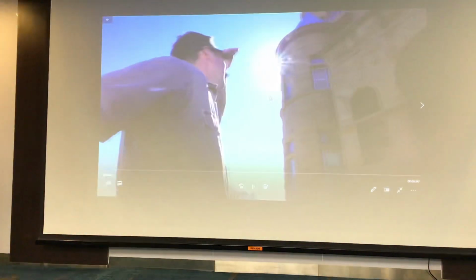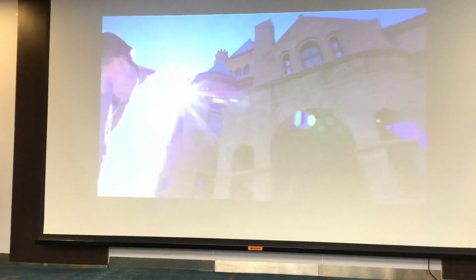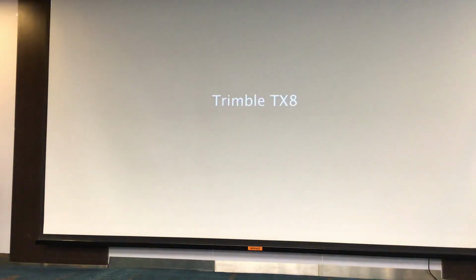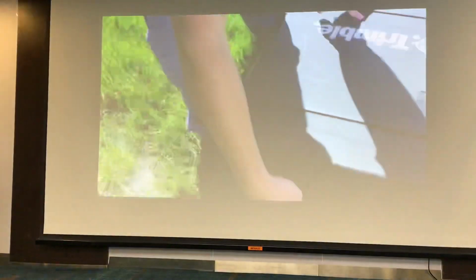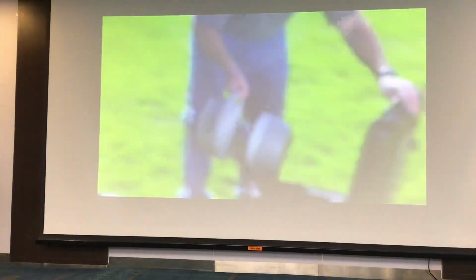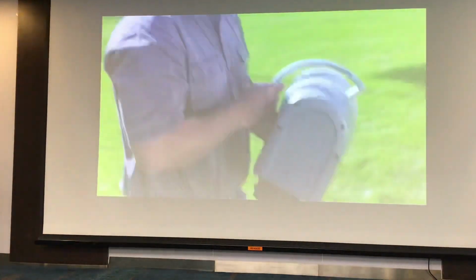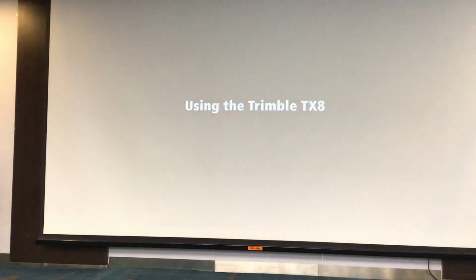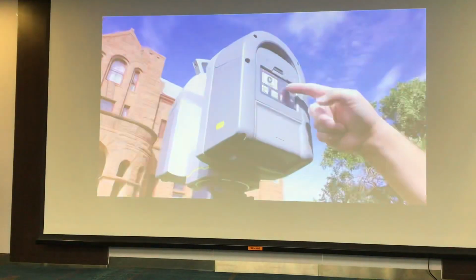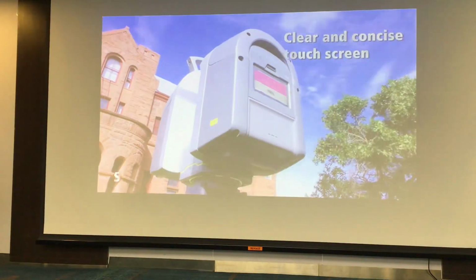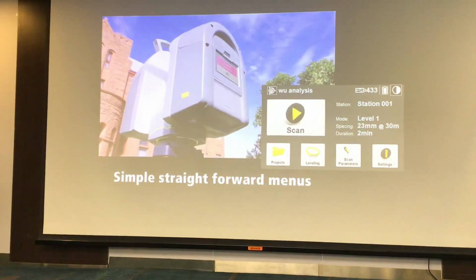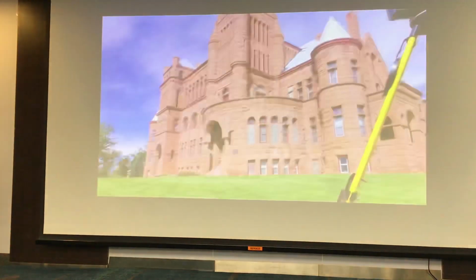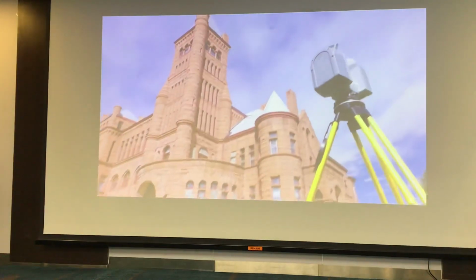A point cloud is a machine that can scan an existing building and create a real 3D model. The model itself is made from billions and billions of little dots, okay? And it's become a way of doing site surveys where you don't have to measure anything, you get the actual structure in the computer. So what you have is a device. There are many different types of devices. You go to the actual project you'd like to scan. You scan it through, you'll see in a moment. Look, it's a device that simply spins around and measures the building, really, with laser scanning.